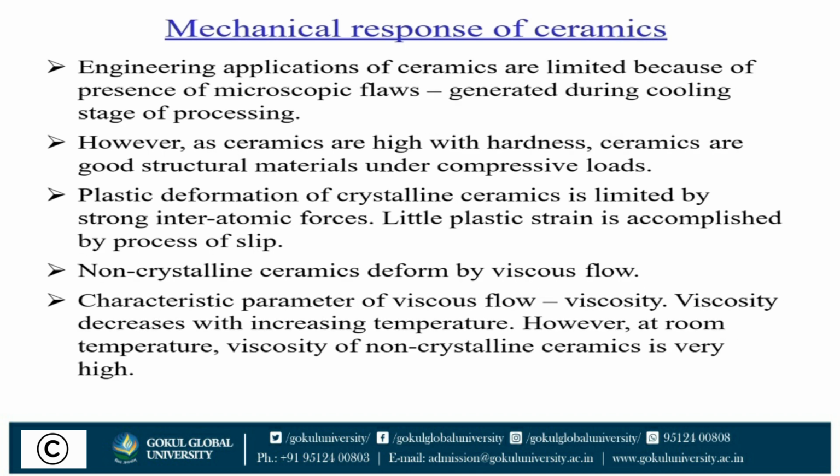The mechanical response of ceramics is limited because of the presence of microscopic flaws generated during the cooling stage of processing. However, ceramics have high hardness. Ceramics are a good structural material under compressive load. The plastic deformation of a crystalline ceramic is limited by strong interatomic forces. Little plastic strain is accomplished by a process of slip.